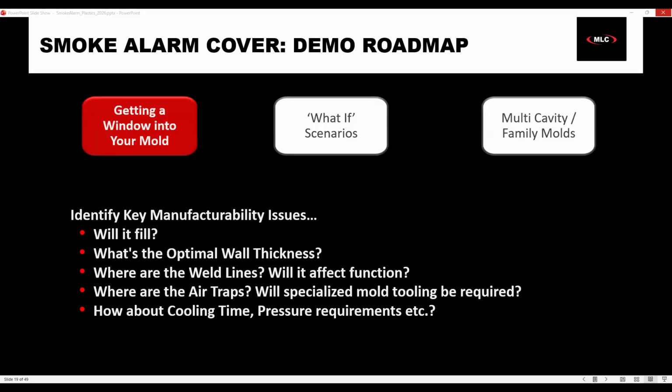Should be able to. And predict the fill pattern. So if I can't get the results I want with one, maybe there's two. And again, I get a different result. So this is a visual tool, but again, just the ability to iterate through some of this information before running a study that could take a while, I think is a really good tool that it has. I'm going to put that back. Actually, I'm just going to cancel out of it. I'm not going to change anything.